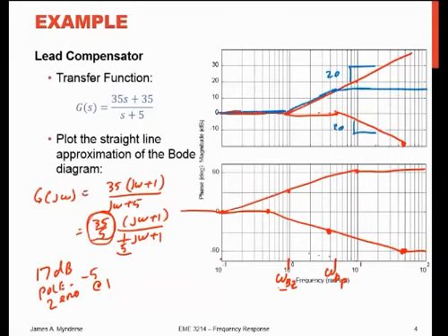In the phase domain, it's much the same thing. Here we're increasing up to that point. Now I have the one term increasing, the other term decreasing. That gives me approximately a flat line somewhere out to here, and then it'll shift back down, and it should hit my 0 point again, because when the two of them add together out here, I've got plus 90 and minus 90. That gets me back to 0 there. So it'll look something like that.